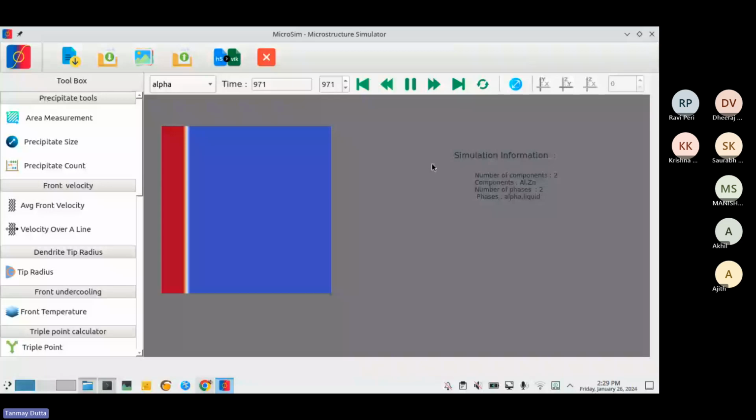So what we do, we want to take a box of this size, and as soon as you simulate some part of the growth, you cut off the part of the solid that is not necessary anymore, and introduce more fresh liquid from the other side. So essentially, translate the box along with the interface. We are moving along with the interface while it's moving. It's called the moving frame of reference. So in that frame of reference, the interface will not change position.